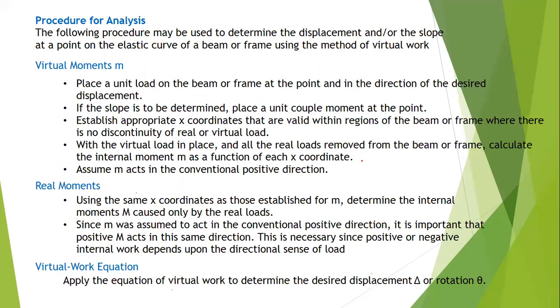Now, the procedure for analysis would be, one, you need to set up your virtual moments. And to do that, you place a unit load at the point where we would like to determine the vertical deflection. If you wanted to determine the vertical deflection, then at that particular point, we will apply a unit load.